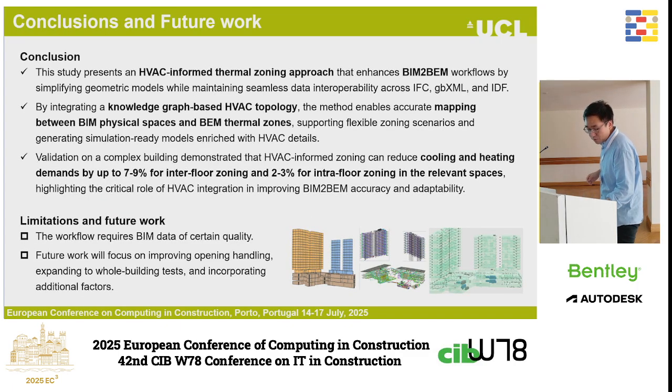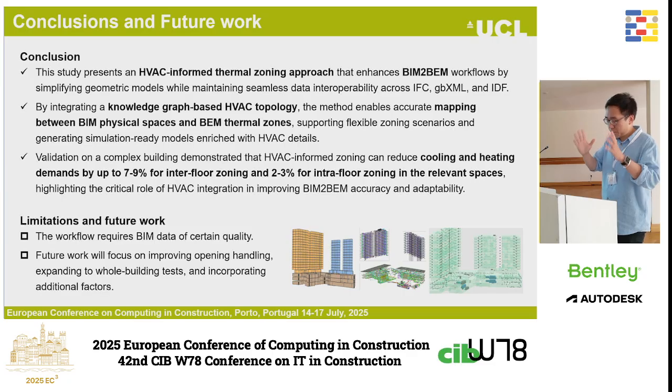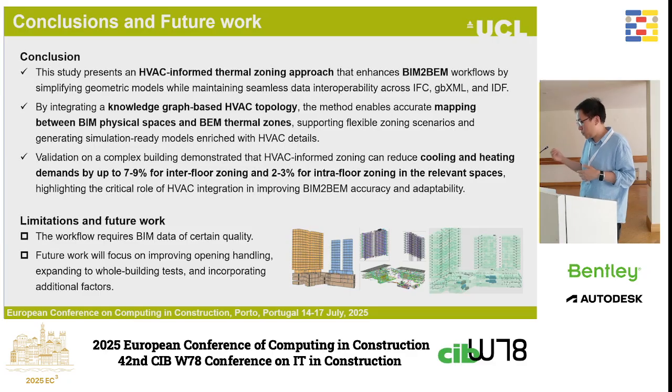Okay, and let me go to the conclusion and the future work. Conclusion: the first one is that we propose an HVAC-informed thermal zoning approach, which can enhance the BIM2BEM workflow and then enhance the seamless data interoperability across IFC, gbXML and IDF. The second one is that by using the knowledge graph-based HVAC topology, it can accurately map between the BIM physical IFC spaces and the thermal zones, and then support flexibility of the building simulation.